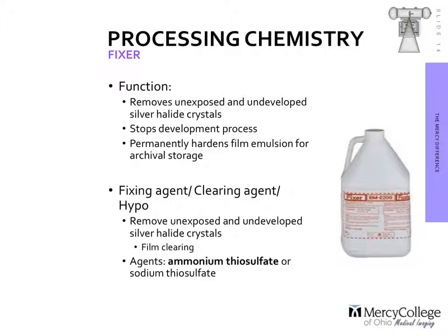So one of its functions is to remove those unexposed or underexposed silver halides. So there is a fixer clearing test, and essentially what this is is that you dip the film into fixer, and it should be a green film, or a never used, never exposed film. And the idea is that it should be clear within 10 seconds at room temperature, or within 7 seconds if your fixer temperature is at 90 degrees Fahrenheit. So that is a test that needs to be conducted to make sure, yes, your fixer is doing what it's intended to do. Yes, you're going to waste a nice clean piece of film, but we need to make sure that the fixer is functioning appropriately.